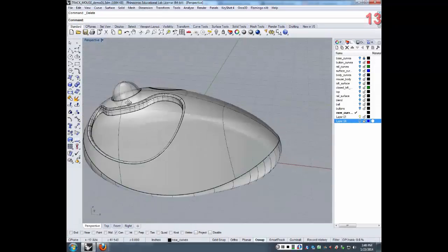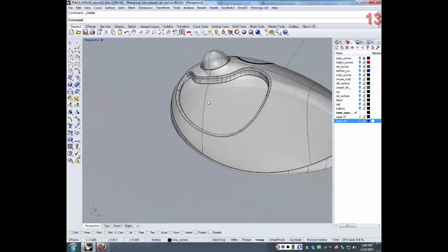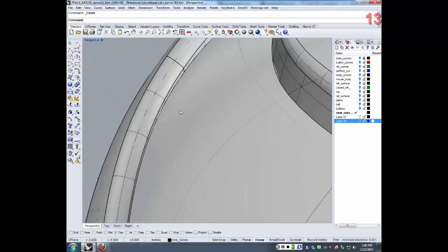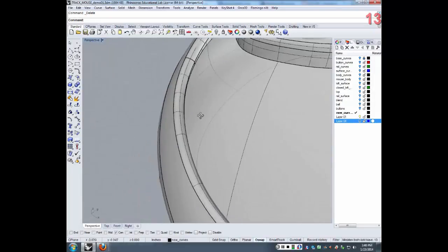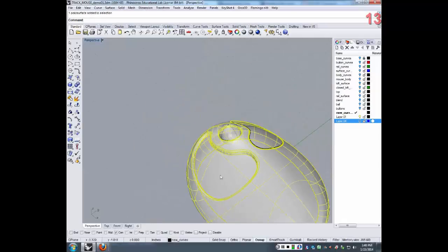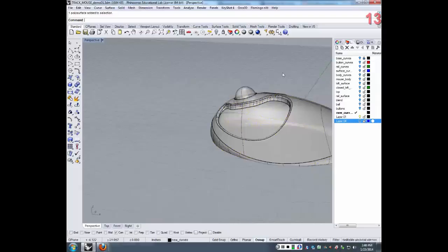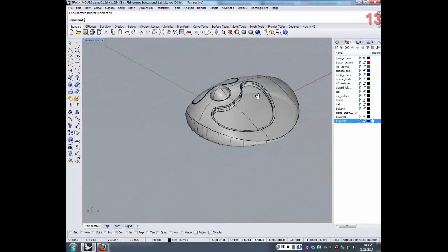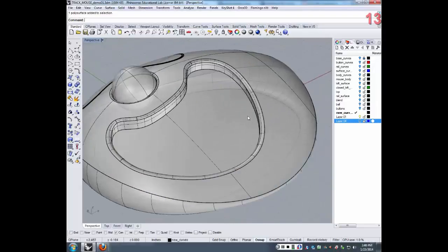Let me see how low that goes. Oh man, I can't fillet that bottom edge at all. You see that? How that converges there? I'm not going to try and fillet that bottom edge at all because that will cause nothing but heartache. Let me back this up.